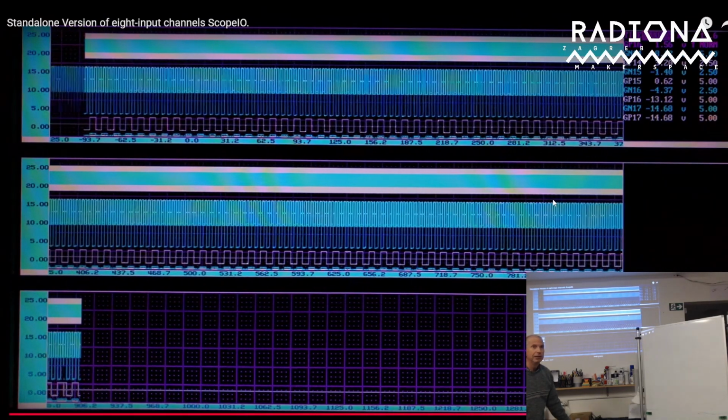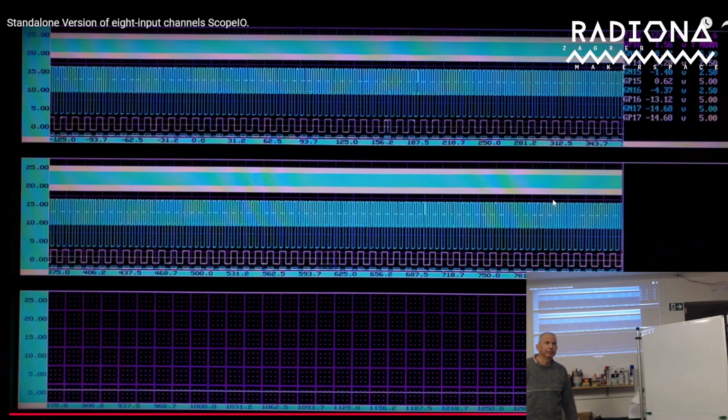So if I may try to summarize it. It looks like an oscilloscope, but the idea is not to make just another oscilloscope, but a tool. Here you are showing the ADCs, because this is just an example, but the cool thing is that you can correlate internal stuff from the FPGA that you otherwise don't see, which is hidden well within the FPGA, and especially at high speed it's difficult to capture the data in the moment, and that's what the tool does.